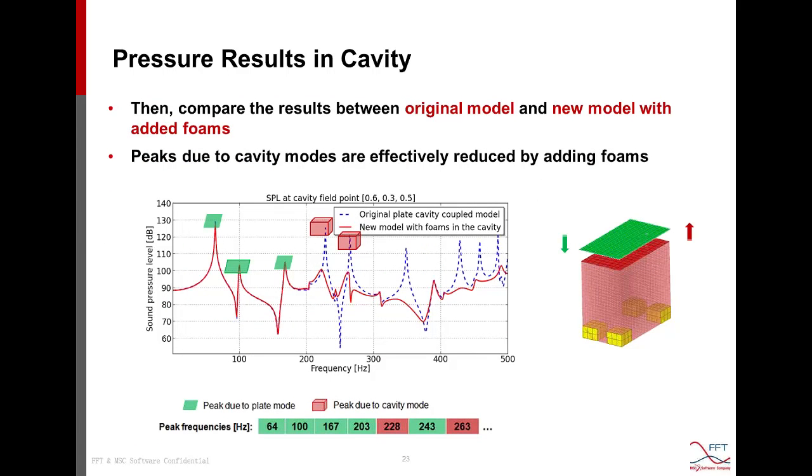And then when we add the foam component on the same microphone, we see that the peaks related to the cavity mode are reduced, this one and this one, while those related to the plate mode stay almost unchanged.